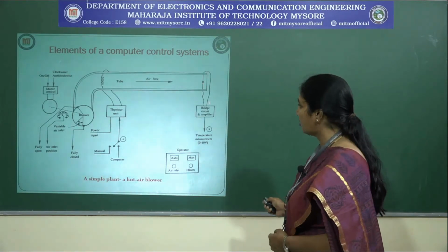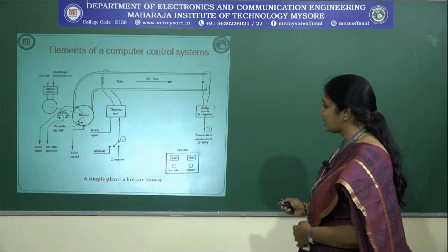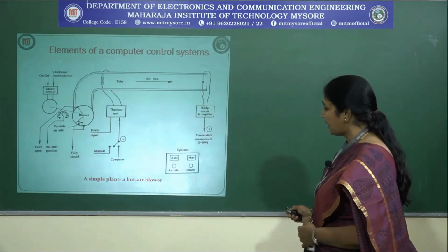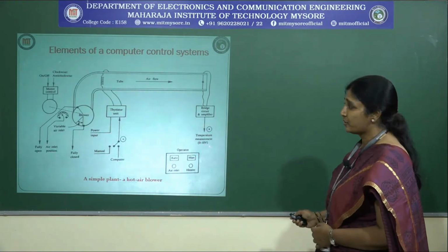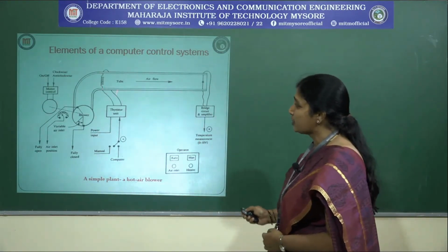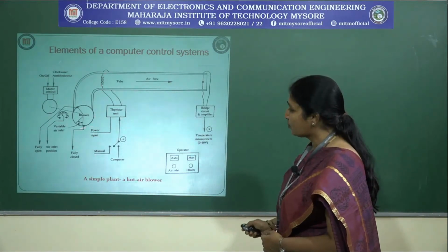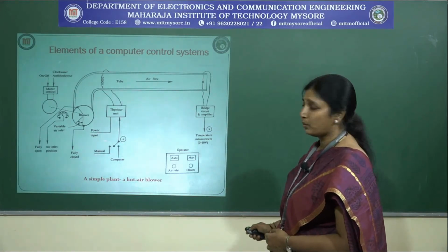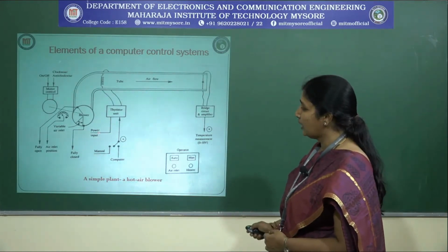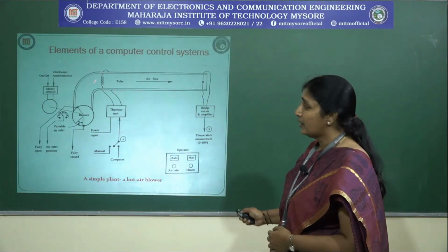One of its ends is terminated across the bridge circuit as an amplifier, the other as a temperature measurement which will be between 0 to 10 volts. And this temperature would be controlled by the power input DC from 0 to 10 volts. So as and when you vary the input voltage, the temperature can be varied.